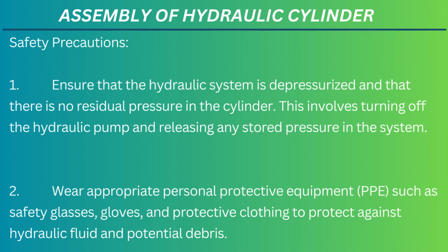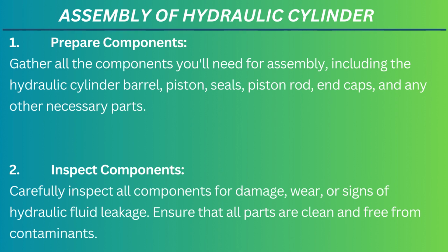Safety precautions. 1. Ensure that the hydraulic system is depressurized and that there is no residual pressure in the cylinder. This involves turning off the hydraulic pump and releasing any stored pressure in the system. 2. Wear appropriate personal protective equipment, PPE, such as safety glasses, gloves, and protective clothing to protect against hydraulic fluid and potential debris. Assembly steps.